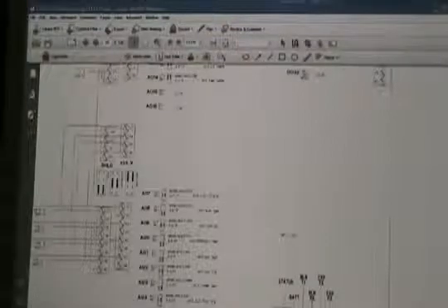If it's a 4 to 20 milliamp input, we're going to send 24 volts out and look for a certain milliamp signal to come back. If it's a thermistor, we won't go up to that 24 volts. It just goes to the two terminals. Okay, so all these are transmitters, and there's our differential pressure right there. And the very bottom one there, TTE4, is just wired straight to the two terminals.